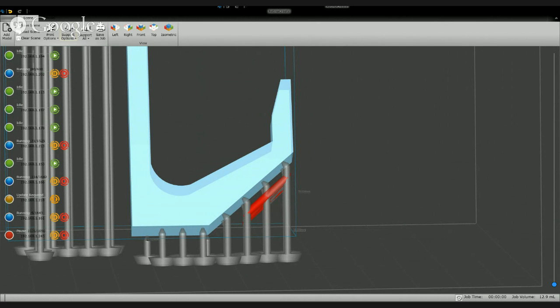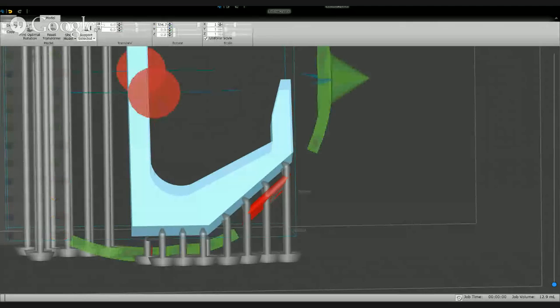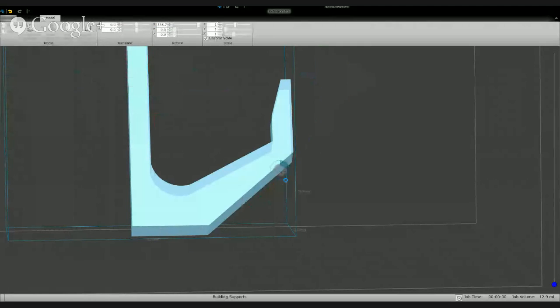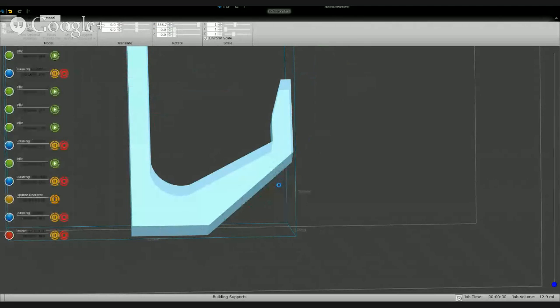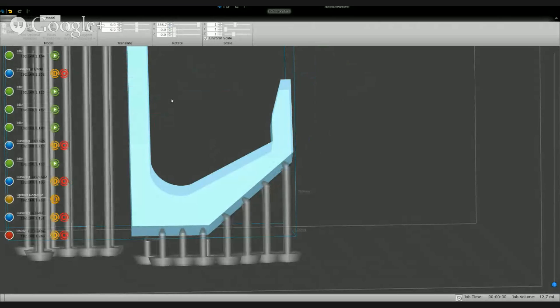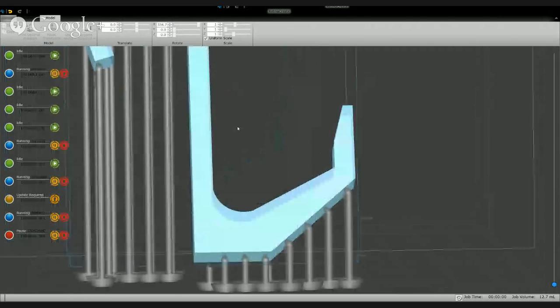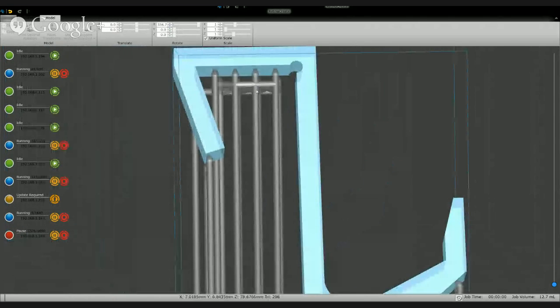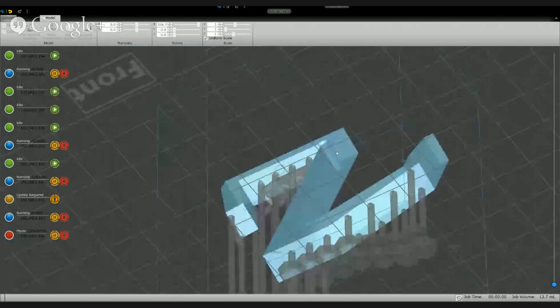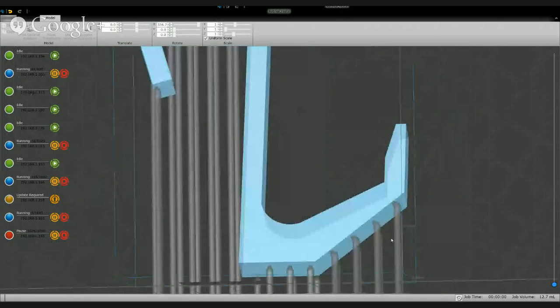So if you increase this to 20, or I typed 25 and said 20, let's do 25, and I support again, you'll see that some of these cross beams will have been removed here, but they'll still exist up here. So these beams are no longer considered tall enough to generate cross beams.